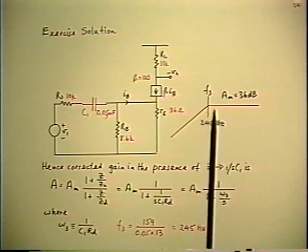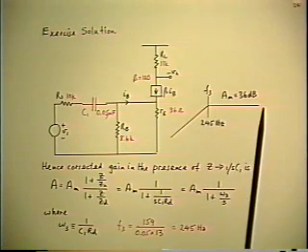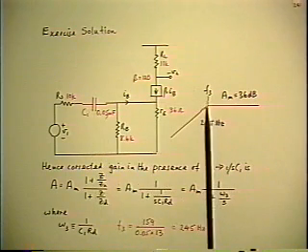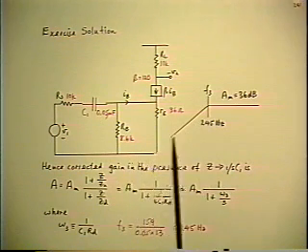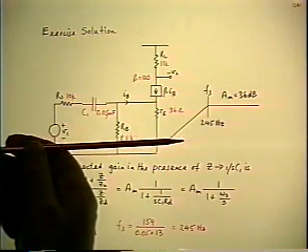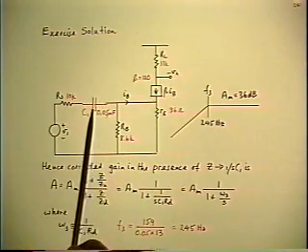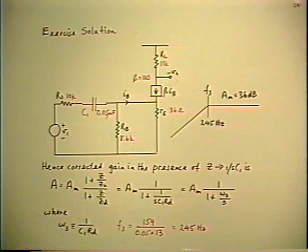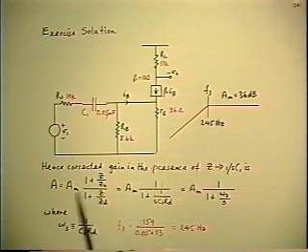So the frequency response is the reference gain at infinite frequency, and as you come down, the coupling capacitor starts to open up, gives you an inverted pole and a drop-off of the gain, and the gain goes to 0 at 0 frequency. It doesn't flatten out anywhere because the capacitor goes to infinite reactance at 0 frequency and, of course, disconnects the output from the input. So you have to have 0 gain at 0 frequency.